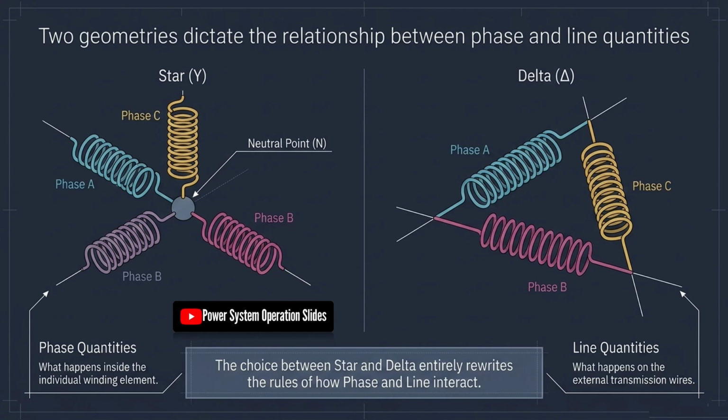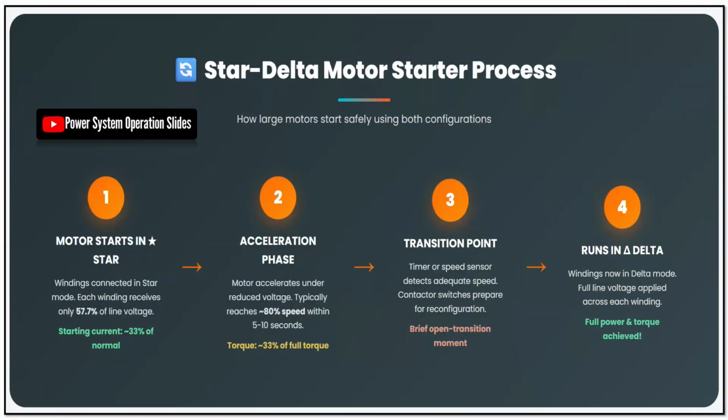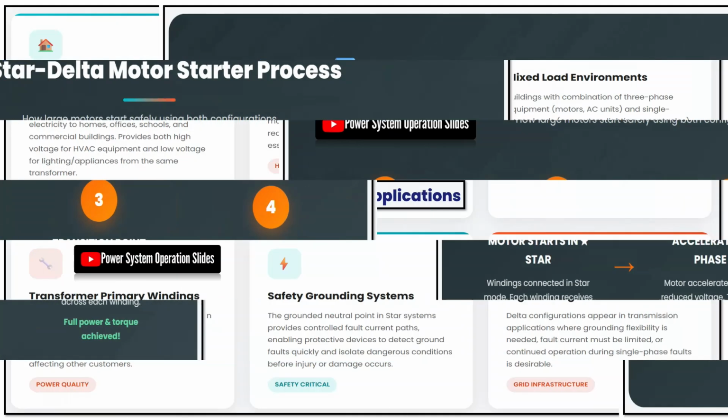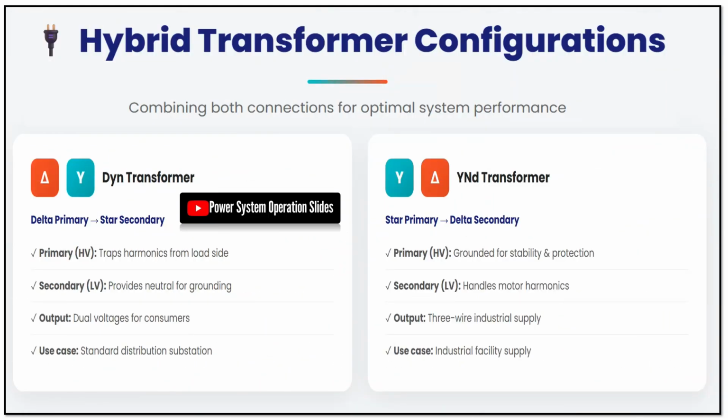The most important voltage relationship in a balanced star-connected system is that the line voltage is equal to the phase voltage multiplied by the square root of 3, which is approximately 1.732. Conversely, the phase voltage is equal to the line voltage divided by the square root of 3. The current relationship is simpler because the line current is equal to the phase current. These relationships explain why a star-connected distribution system can provide two useful voltage levels from the same electrical infrastructure.